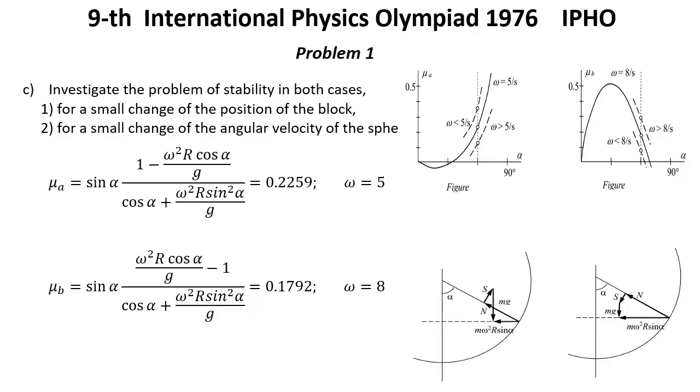The same thing for angle alpha. Suppose that we decrease alpha a little bit, then we don't need more force of friction to struggle against it, and the body will stay at this angle, which is a little bit less than critical. But if we increase alpha, we have to increase our critical force of friction, and the body will go back. So we investigated all these cases.